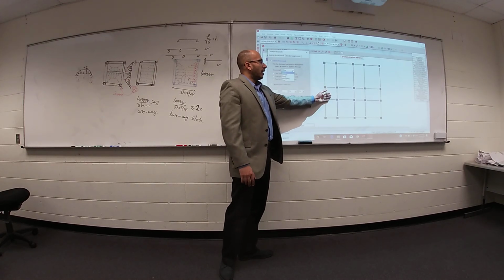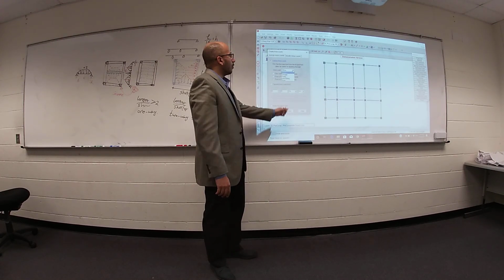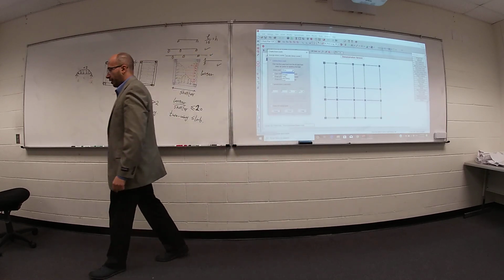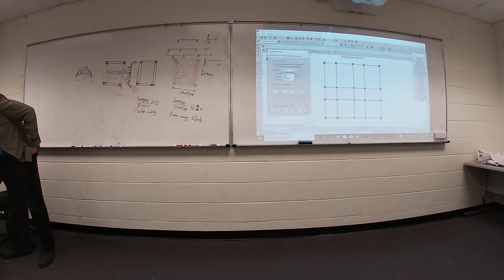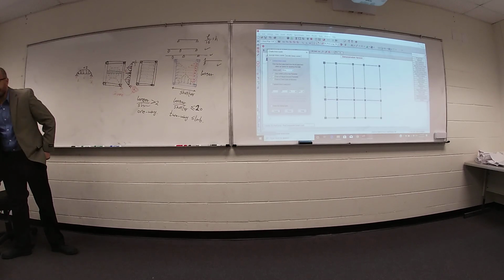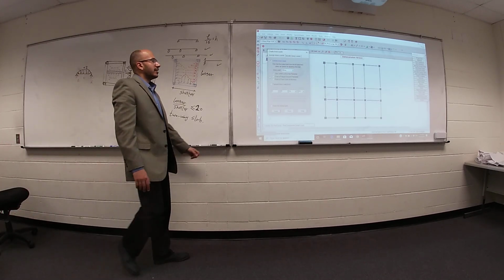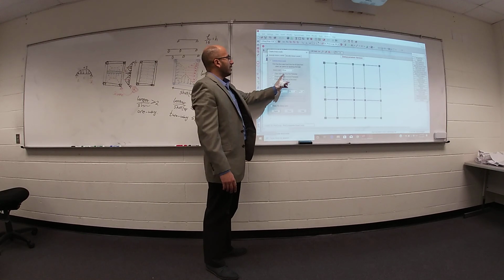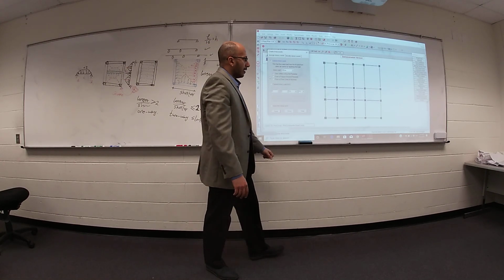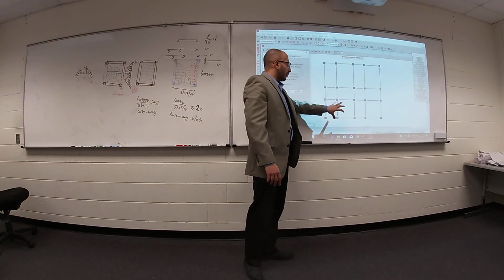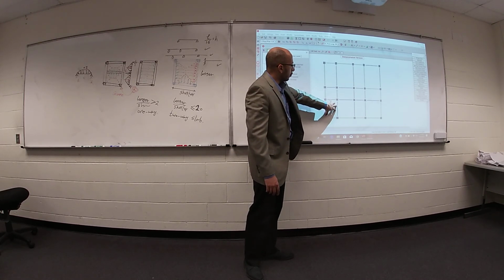So I would like to select the type of your plan. I will use office, and I will use the first option. Just click within your area. If you click here, you define live load on this area.